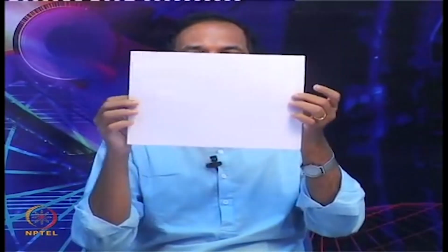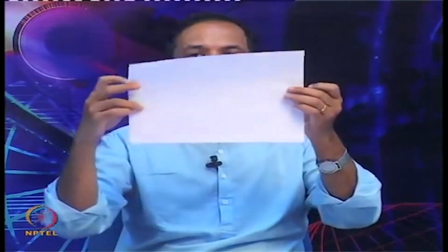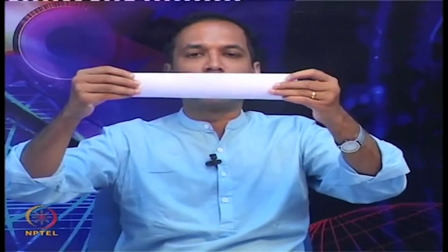So, one way to think about this is you take a paper like this, right. If you put up entries here, you know the adjacency right away. If you write it in the order 0001, 1110 and so on, you know what adjacency is. What else is adjacent is if you are able to roll the paper like this, right. So, what I did is I had a table like this. If I roll a paper like this, whatever cells are adjacent we call them adjacent also, or I have a table like this and I roll a paper like this, one row folding into another, whatever cells are adjacent they are adjacent in K map sense.